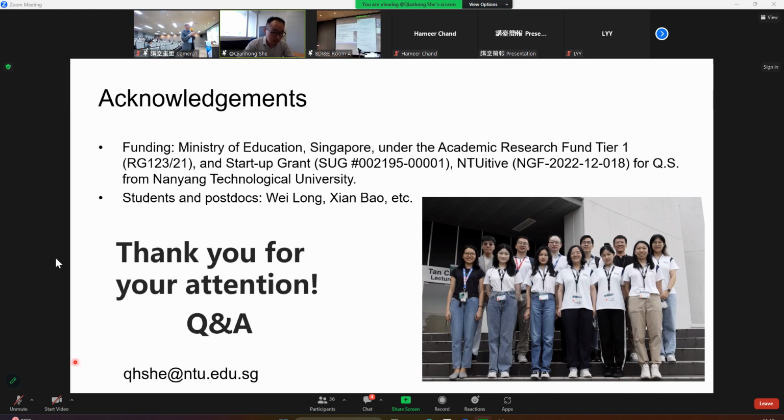The results show the increase in pH as the voltage increases. However, the study has been investigated up to 4 volts. What happened when tested above 4 volts? It seems it's not equilibrium voltage. As we mentioned, at high voltage, there is a higher change of the pH. But actually, for the first system, the flow-by EAR system, we do not think it is really promising. We just did that research to demonstrate the concept. But for real applications, my opinion is that we should consider the flow-through system. And also the voltage at 4 is very high, and there will be many other reactions. So that is also not good for the electrochemical system, not good for the electrodes or membranes.